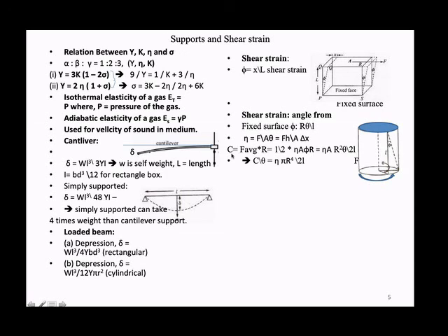Now we have a torque per unit theta. This is the torsion strength of a wire or a cylinder. We have a torsion strength, a couple for theta. When we substitute the above things, putting area as pi r square, with the rigidity modulus, it is pi r to the power of 4 by 2L. L is the height. So this is the torque per unit length.